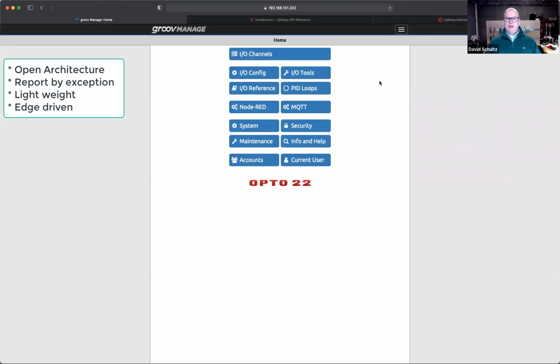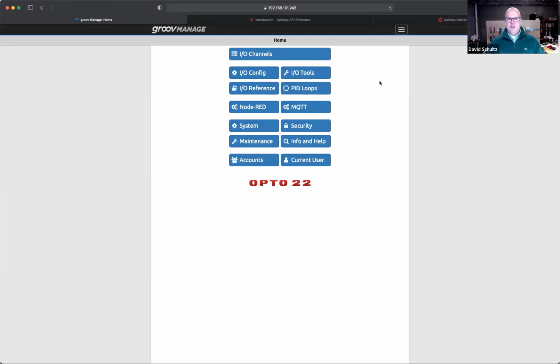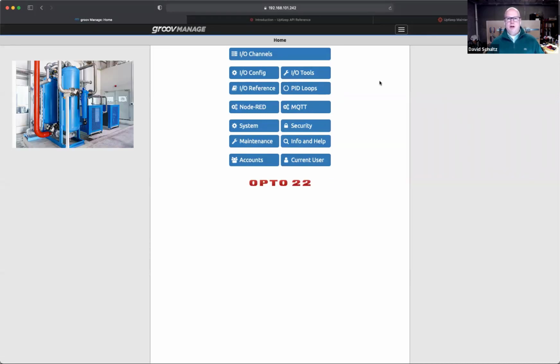So we talked about, once you get into the various strategies around your maintenance and reliability, they always need to be technically feasible and economically viable. And oftentimes that means, especially for remote assets, it's either going to break, or there's going to be some kind of preventive maintenance, so every so often you go out to the asset and do some work on it. Well, this is the next strategy up the hierarchy, if you will. We're going to do condition-based maintenance.